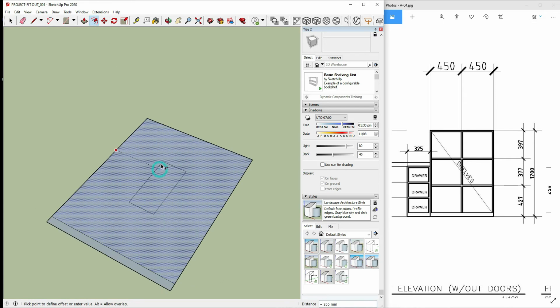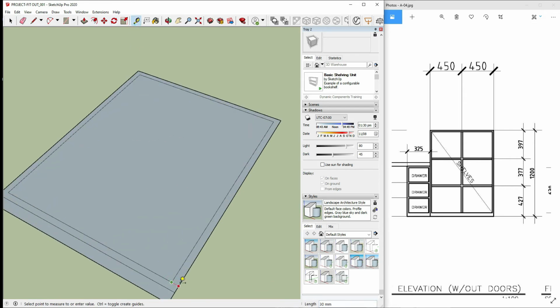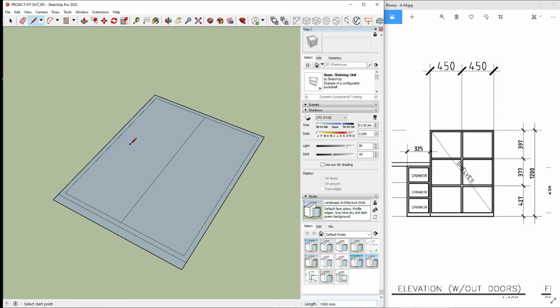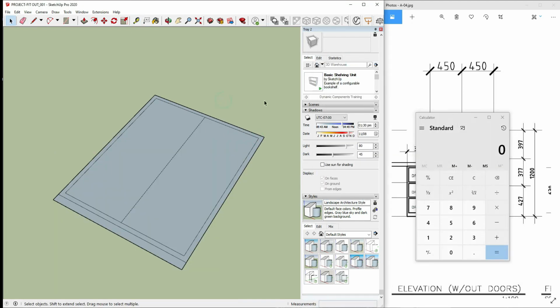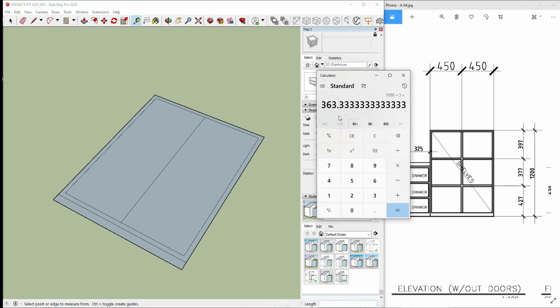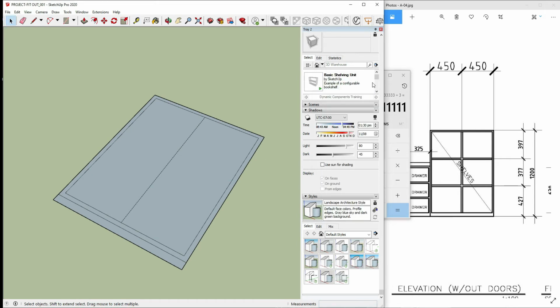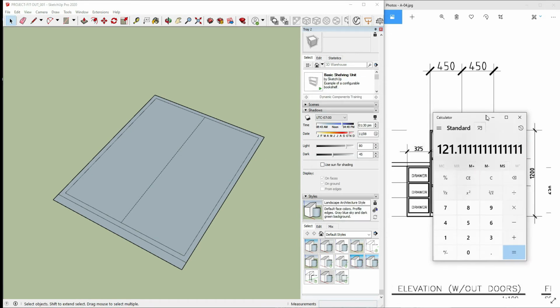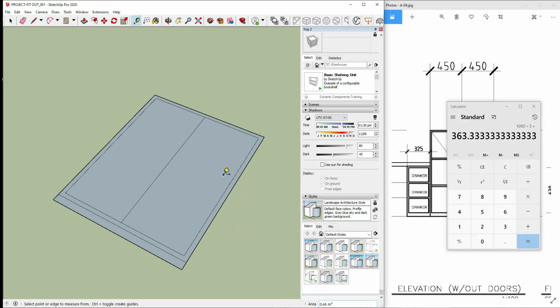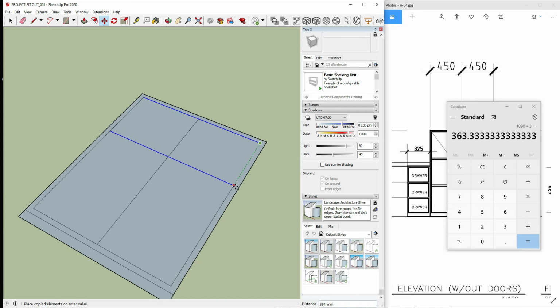We start with making the rectangle and placing the exact dimension details in the SketchUp Dimension tab. I used again the Offset tool to create the wall line easily and used the calculator to check the dimension. Here, I divided the vertical line by 3 and copied a line to create a division of the wall line, which is the same as in our reference.